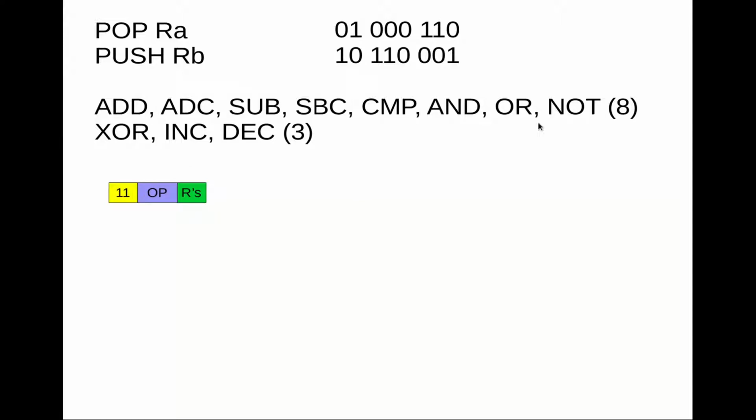And so to encode 8 values we're going to need a minimum of 3 bits, because you need 3 bits to express a number between 0 and 7, so any of a possibility of 8 values. And in fact, if we want to encode the nice to have instructions as well, we're going to need more. We're going to need 4 bits to encode just the operation. So we have these 2 bits fixed to say we're dealing with an ALU, because any other combination of these 2 bits is used by all of the other instructions which don't really involve the ALU. And so for the operation we're going to need either 3 or 4 bits.